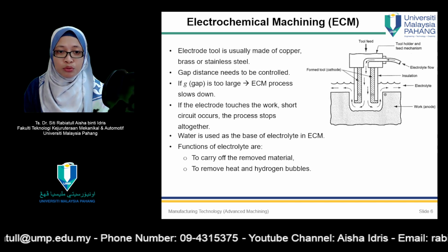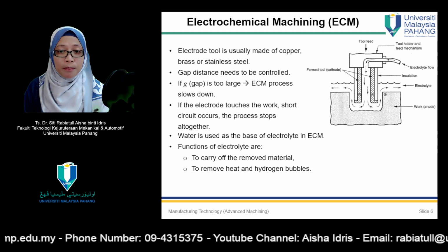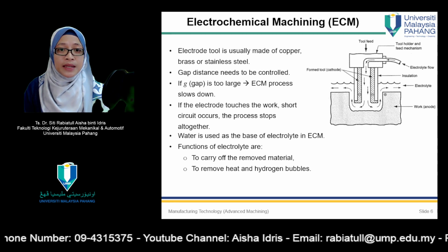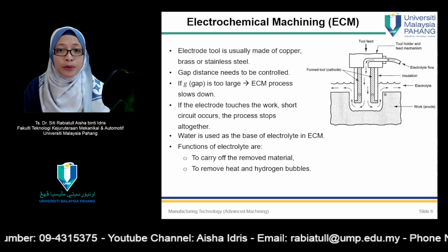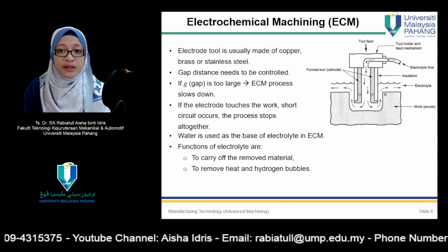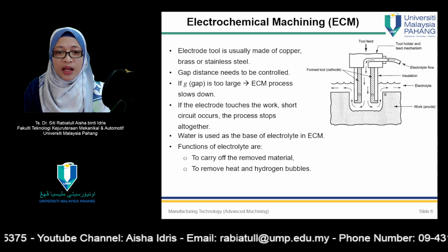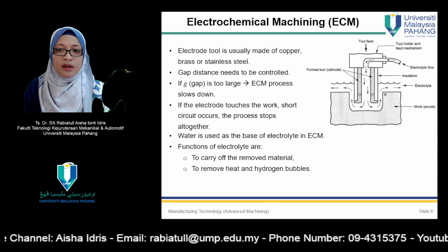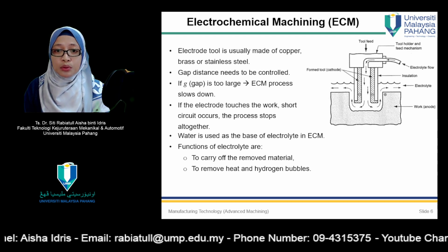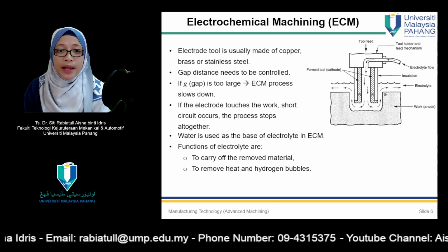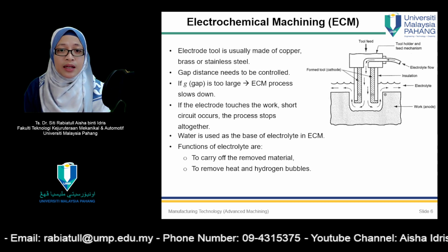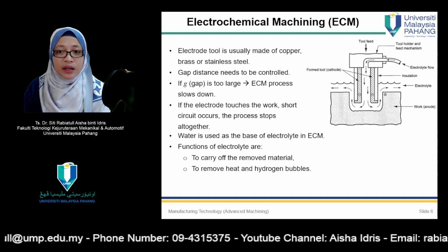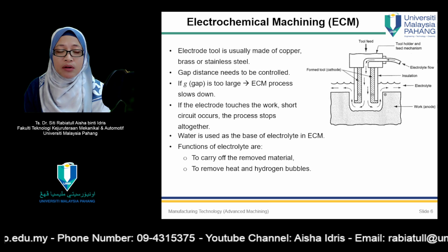The electrode tool, usually made of copper, brass or stainless steel, is designed to possess approximately the inverse of the desired final shape of the part. An allowance in the tool size must be provided for the gap that exists between the tool and the work. To accomplish metal removal, the electrode is fed into the work at a rate equal to the rate of metal